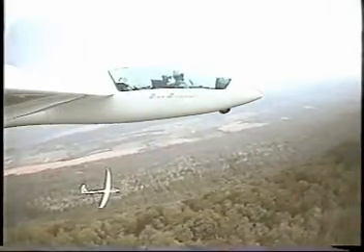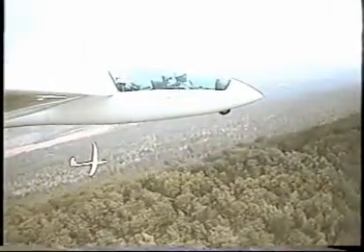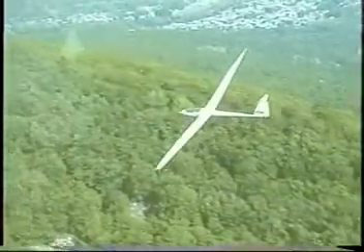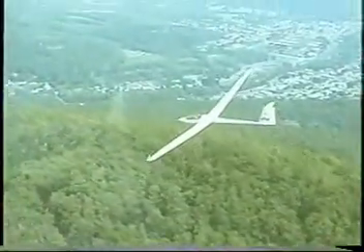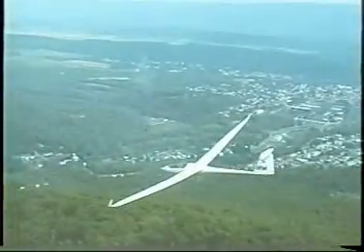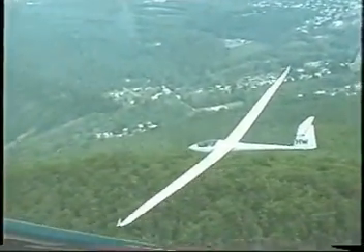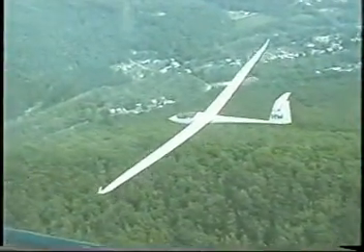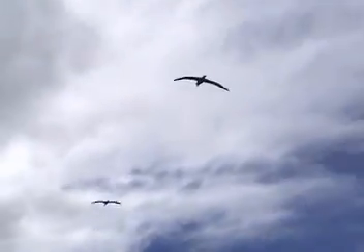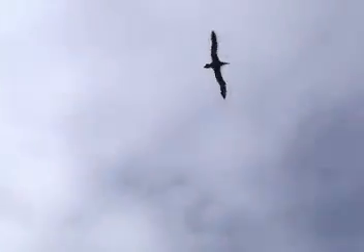The airflow over a glider wing is approximately two-dimensional as well, since the wing's span is much larger than its chord. Such a wing is said to have a large aspect ratio. In this case, the wingtip and root are so far from a section at mid-span that they may as well be infinitely far away. A similar argument can be made for the wings of this waved albatross, more than 3 meters in span.